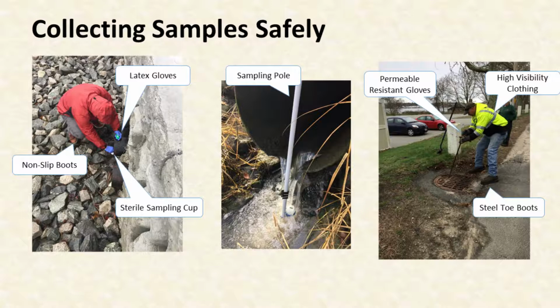In addition, those involved with lifting manhole and catch basin covers should wear steel-toed boots and protective gloves. The cover to these structures weigh upwards of 250 pounds and can cause serious harm to underprotected personnel. Only properly trained and authorized personnel should be lifting these covers. All others should stand clear.